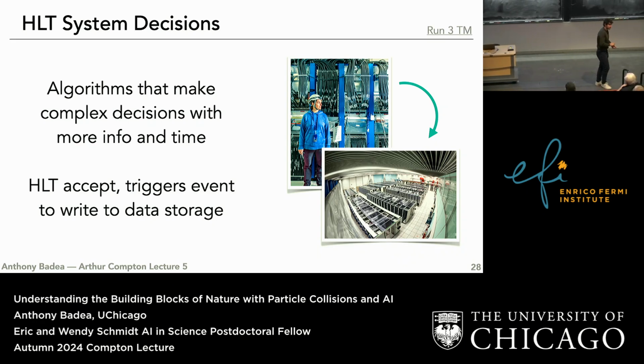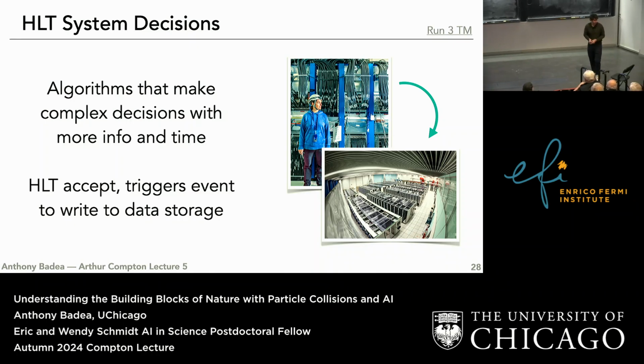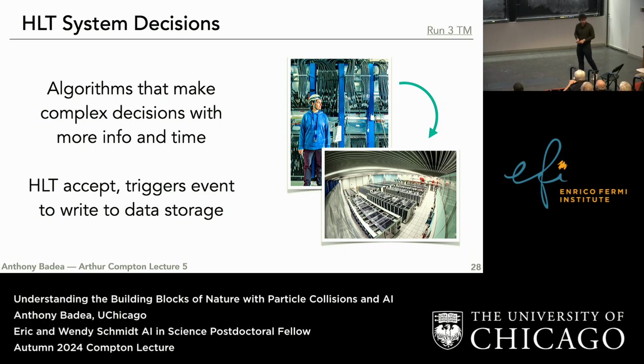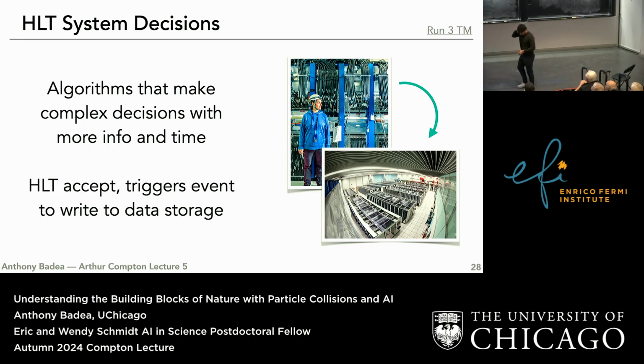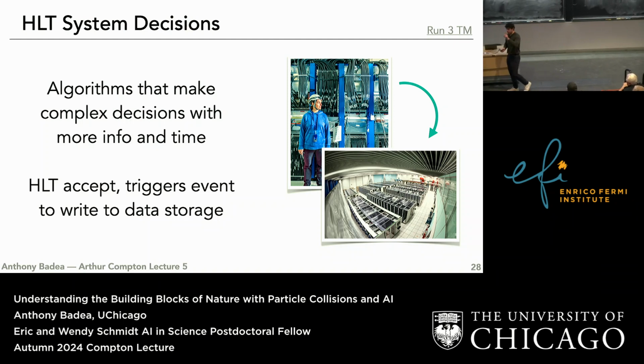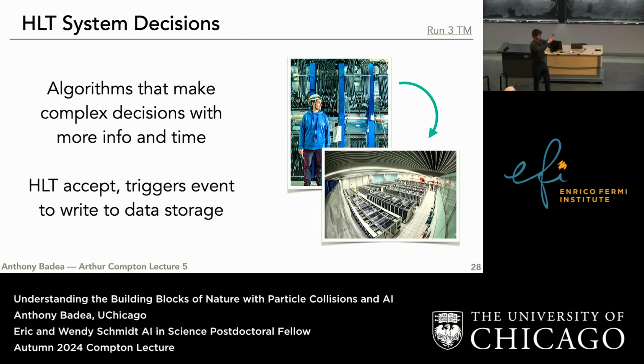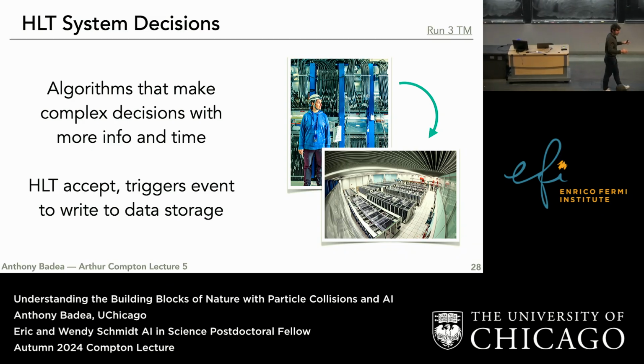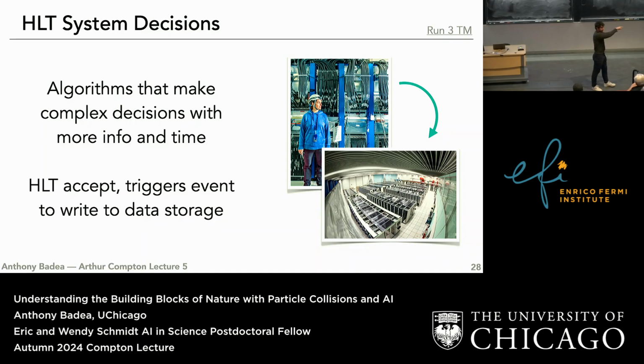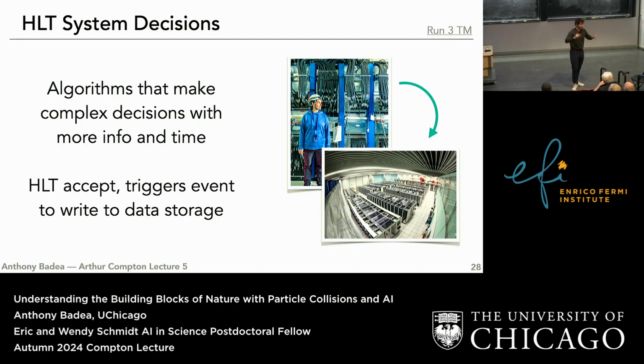Yeah. So the first stage, the level 1, does it also tell it where in the detector to look, so you're not even looking at the other sensors at that point, you're only reading from the region of interest? Yeah, so the question was, it sounded like the level 1 detector, this first stage, not only output a coincidence, but it also told you where the second stage should look. And yeah, so what it does is inside of the algorithms, there's effectively a lookup table where it says, I see a coincidence at this point, and then you map that point to a physical location on the detector.